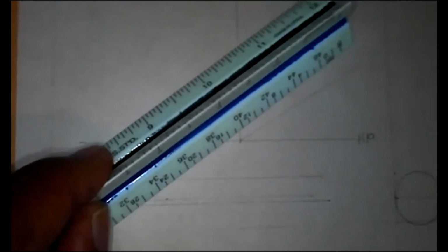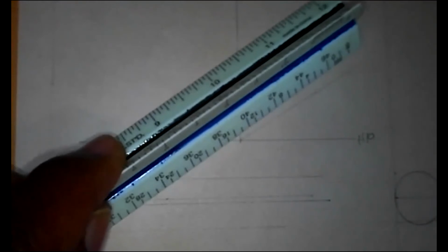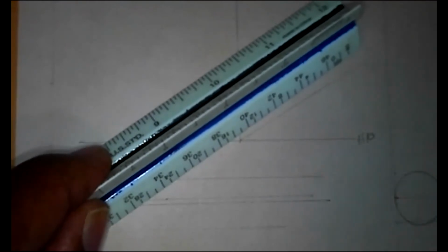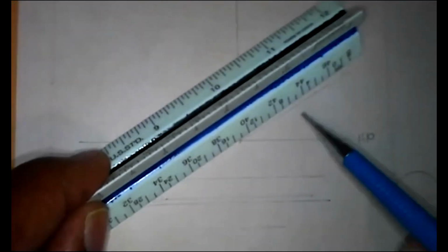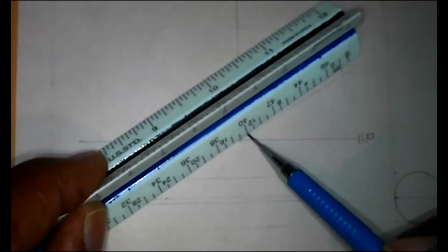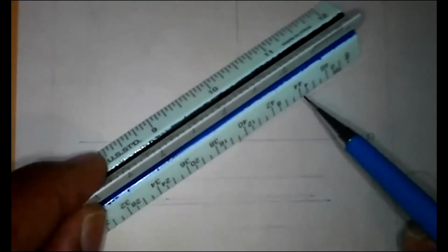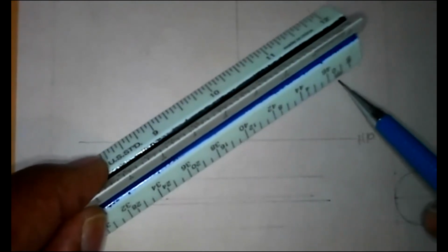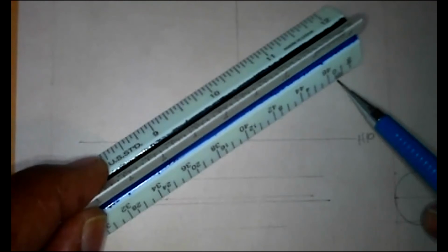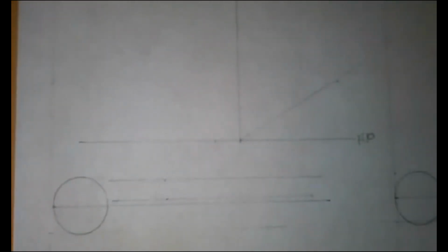Okay, I'm going to go to the 1/8 of an inch scale. Let's find that 1/8 of an inch. There it is. Okay, this side. All right, so I'm positioning my scale parallel to 30 degrees. Okay? All right, and I want to go 14 feet. You see, that's 0, that's 12, 13, 14. All right, so that's 14 feet. So my building will end right there. That's pretty good. All right, so that looks good.